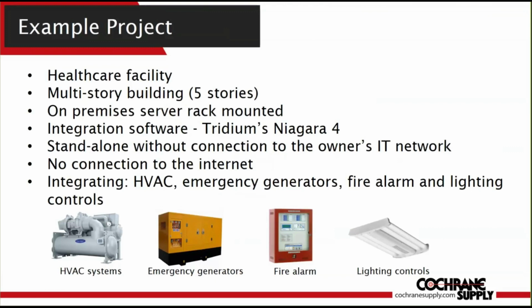Okay, so we showed you the slide earlier today that we're going to mount all of our hardware in a rack, right? The integration software we're going to use is Tridium's Niagara 4. I mentioned it earlier that it's going to be standalone with no connection to the owner's IT, no internet connection. And in today's example, we're going to actually integrate 4 different OT systems. We're going to integrate HVAC, emergency generators, fire alarm, and lighting controls.